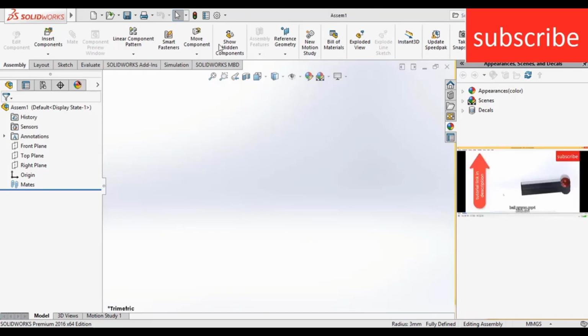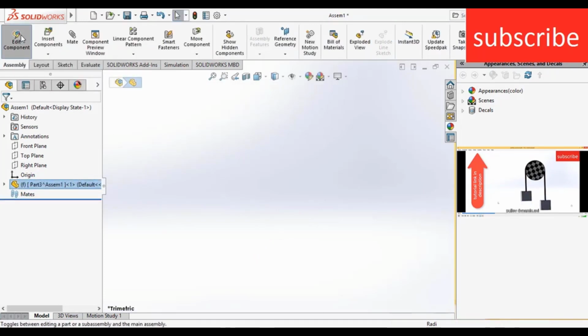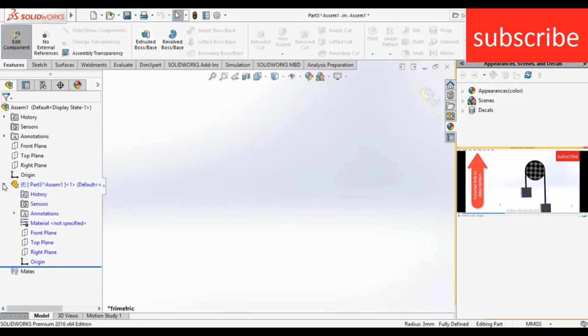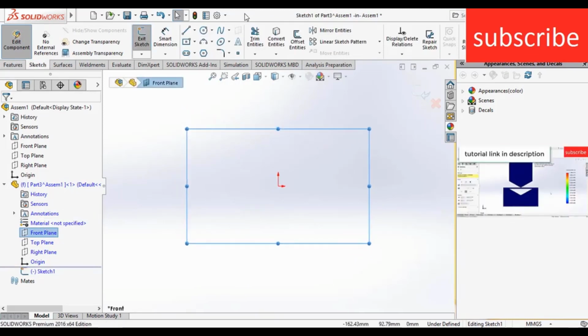So basically I am doing all this in assembly mode, not in part mode. So first of all we need to create a new part. Click on this part, then click here, click on edit component. Now go to the part, select the front plane, click on sketch, press Ctrl+8 for normal view.